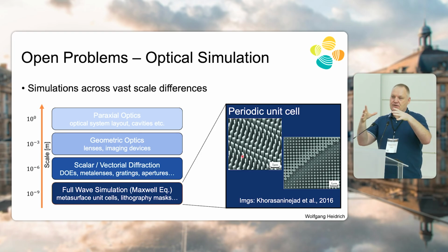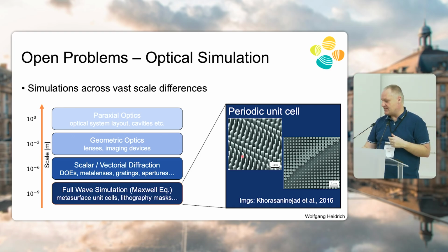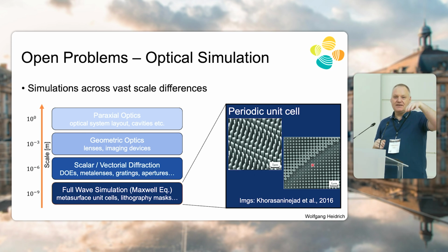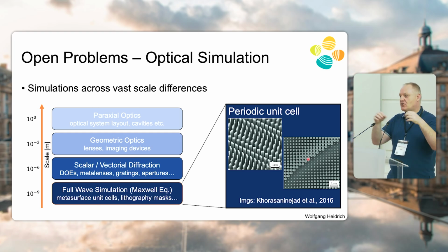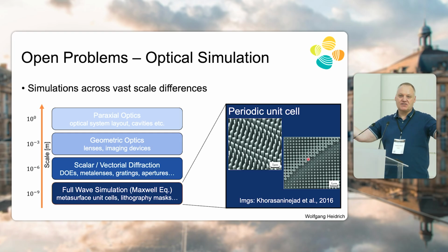The problem is that when we do this pre-computation, we're tiling the whole plane infinitely with the same nanostructure. And then we say, okay, this one is phase pi and this nanopillar is phase 2 pi, and we put them right next to each other, because here we want a modulation of pi and here we want a modulation of 2 pi. So we just place the nanostructures right next to each other in a completely different neighborhood than what was ever simulated.